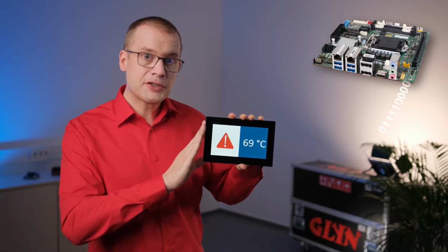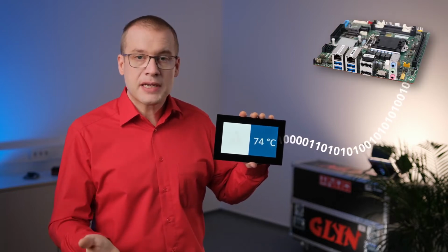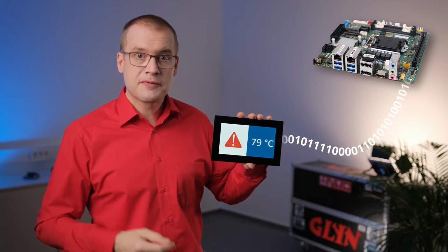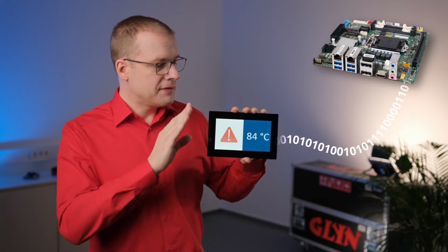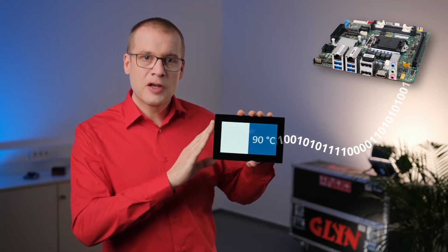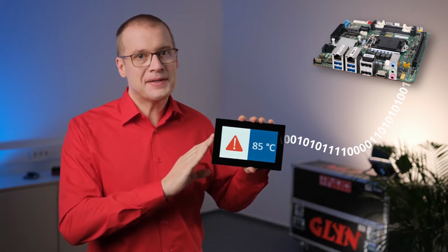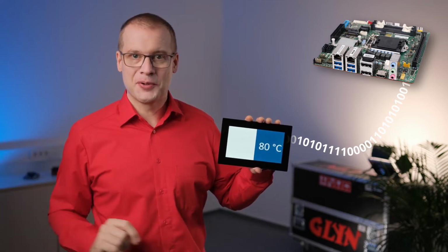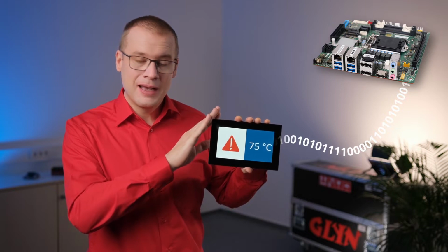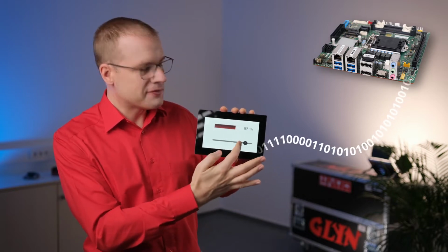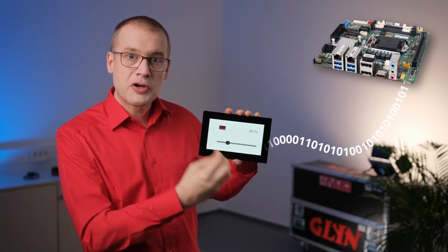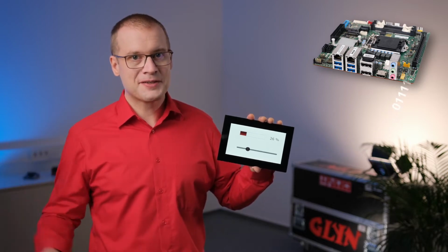It receives the information such as metering data or the status of the application. And because of the Cortex M7, all the graphics are rendered independently of your main MCU. It's all being done here. Now, if a user interacts with this device, then this information, the commands, can be sent back the same way.